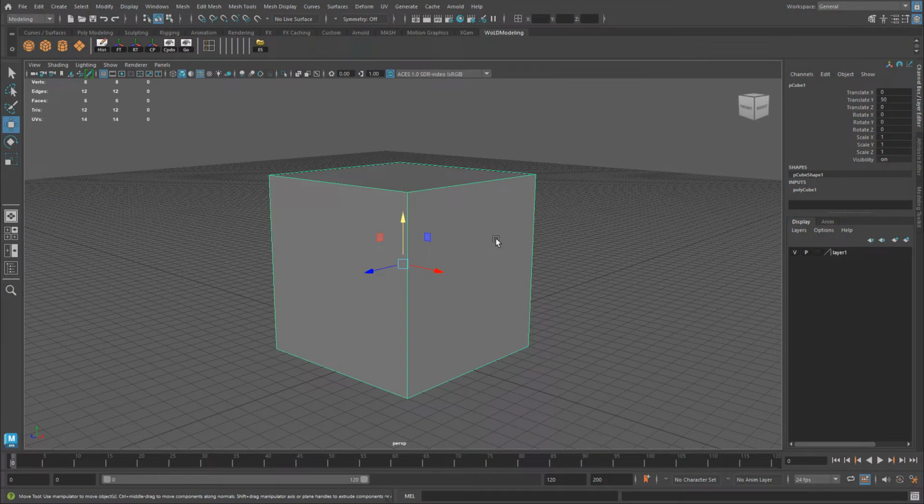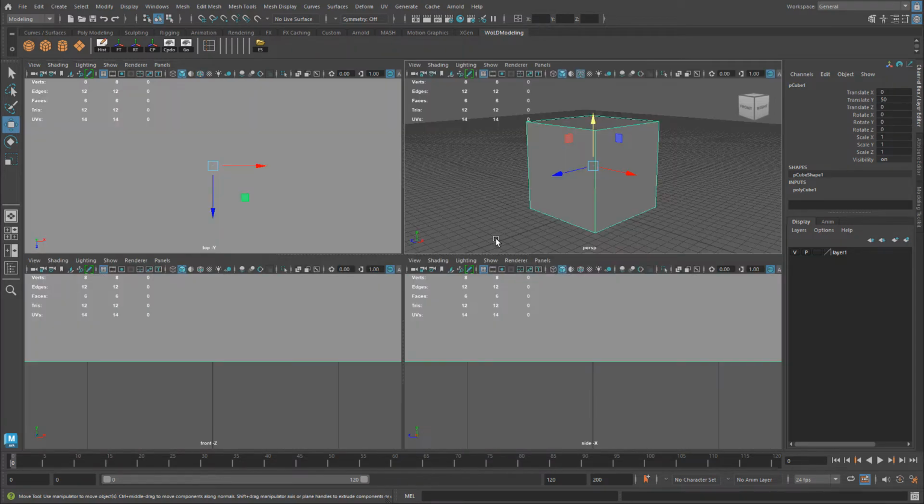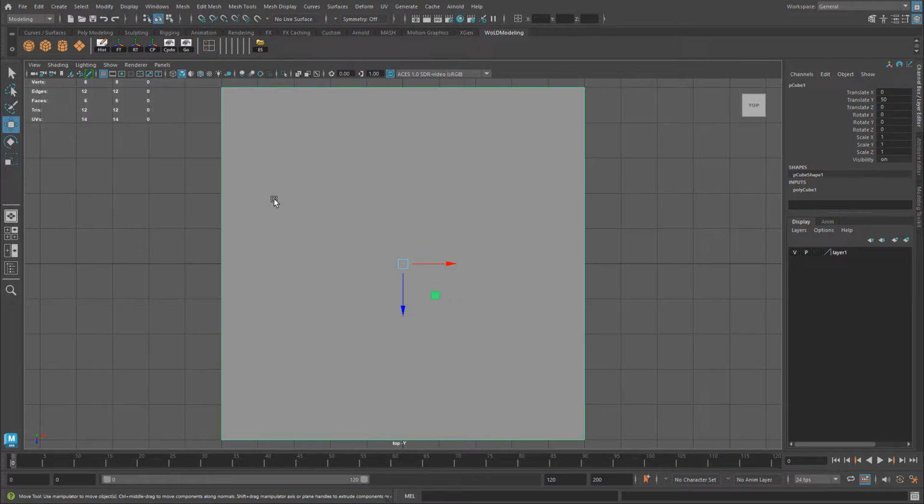And to navigate inside the orthographics, you just need to know 2 shortcut keys. So I'm going to hit Spacebar to get access to the orthographics. Now, right now they are in shaded mode, and I'll show you how to switch over to wireframe a little later. But I'm going to go ahead and maximize the top view, place my mouse in the top view viewport and then press spacebar to maximize it. I'm going to hit F to frame that object.